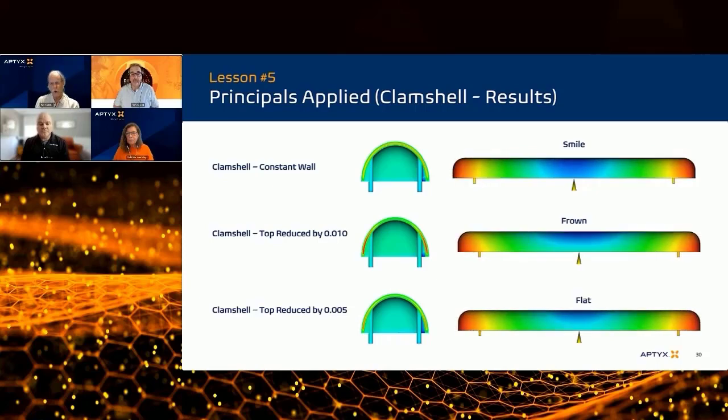It worked. Now, in my experience, that technique works, but only for minor change. If you have significant geometry driving your shape, most of the time you're not going to get there with just a mold temperature change. The last thing to worry about is the thermal expansion deltas. If one side is hotter than the other, the bigger the tool is, the more dangerous that becomes with all your fits and shutoffs. Ryan, do you have anything to add to that?